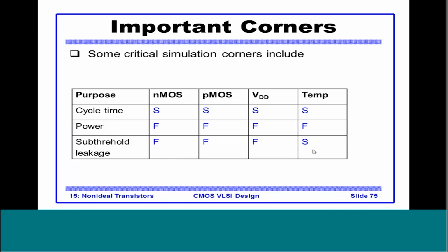There is no need to fret a lot about this corner information if it is not clear at this point of time. This will become very clear when we look at units 3, 4 and 5. But please remember that a fabrication process is not ideal. There are hundreds of parameters, and most of these parameters exhibit an average value and a normal curve kind of distribution.